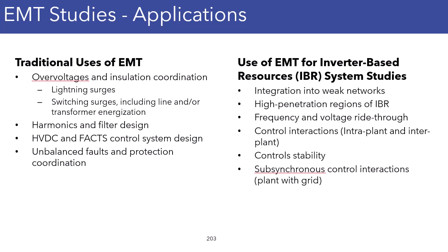You see over on the left the traditional uses of EMT, and over on the right you see the use of EMT for inverter-based resource system studies, and you see instances in which it's more likely that an EMT study is needed. EMTP, by the way, was the former terminology for EMT, but this is where EMT studies are going to really come into play. Integration into weak networks, meaning radial types of networks or networks that don't have a lot of generation connected into them. That's what weak means.